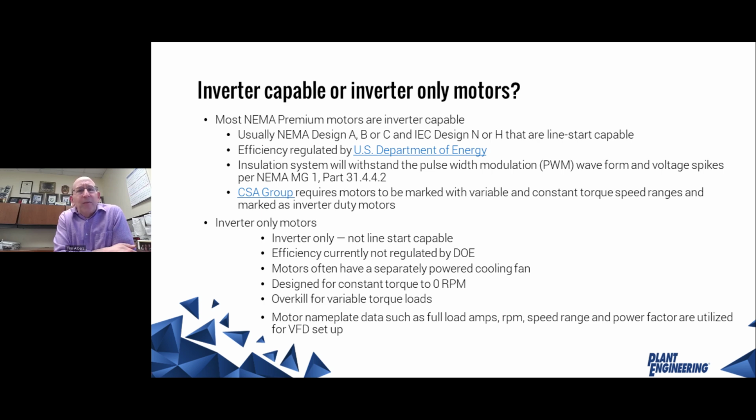Definitely an overkill motor for a variable torque application such as a pump or a fan. So what I'm telling you is most motors are going to be capable of running on an inverter. Be careful of saying I need an inverter only motor or the best inverter duty motor. If you're running it on a pump or a fan, you may not need that, and you might be spending a little bit too much versus what you really need.